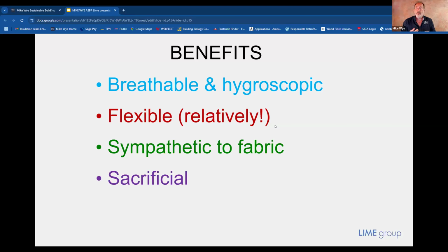What we want to achieve is a state of equilibrium so that moisture which arrives can then vacate again. The wall will be in a state of balance. We won't see an undue accumulation of moisture, which can have major issues with the fabric of the building and the performance of the wall thermally as much as anything else. The mortar joints, therefore, in a more permeable lime mortar will allow further vacation of this moisture content. If we have cement in that position instead, it can cause the moisture to become trapped in the wall.